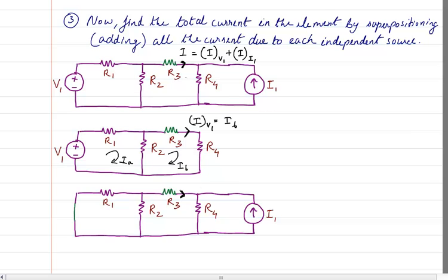They will draw the direction and give it to you, or they will not draw the direction. If they have drawn the direction, take only that as the direction, and that same direction should be taken in each and every case. So this one will be I, the current I, because of source I1. And if I am going to use mesh analysis, or even nodal analysis, let me use mesh analysis because that is the preferred choice of most people.